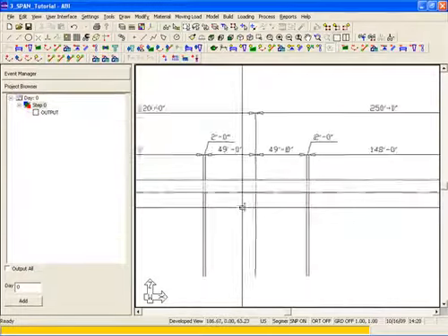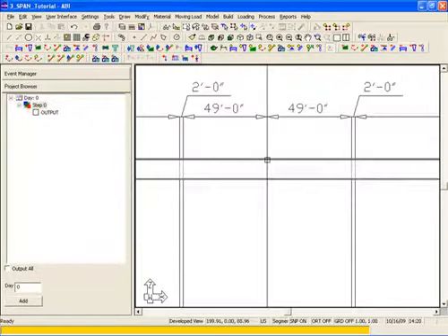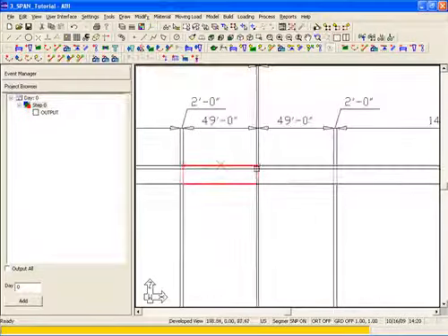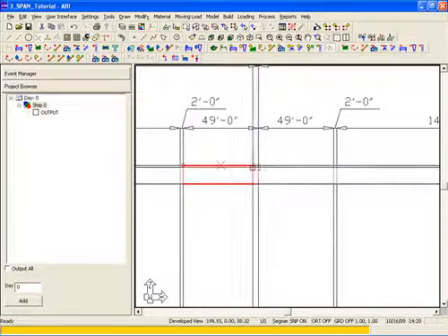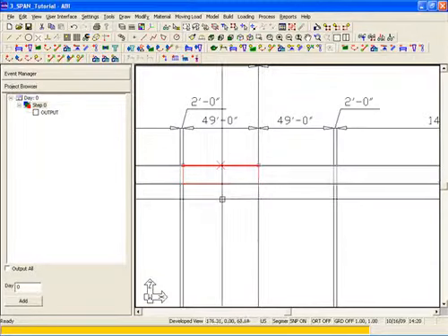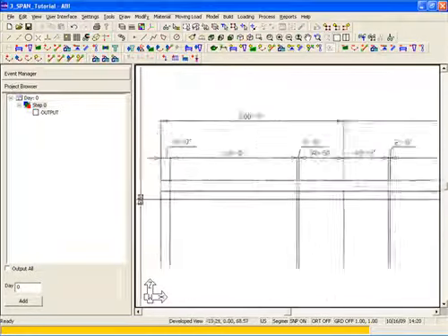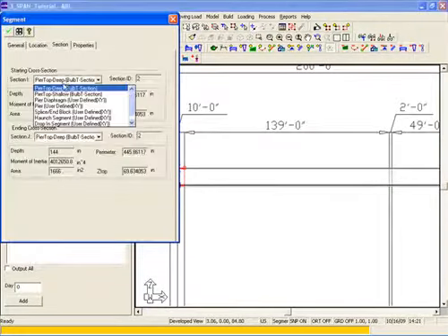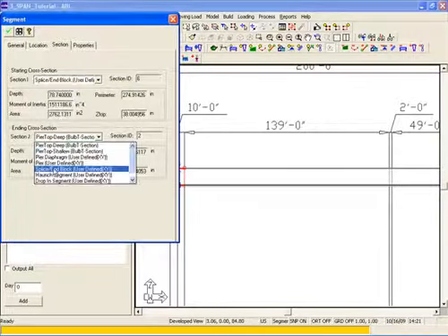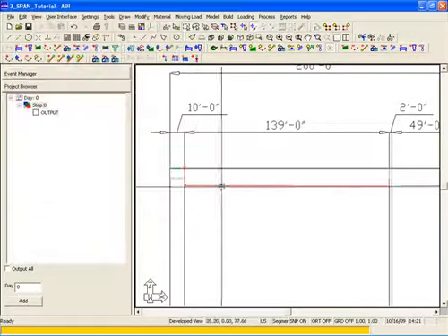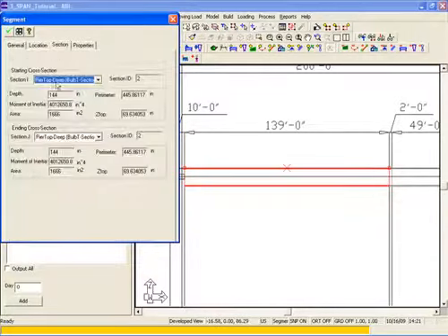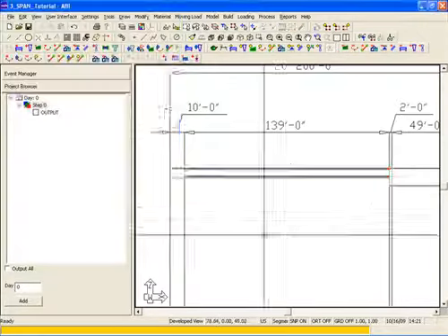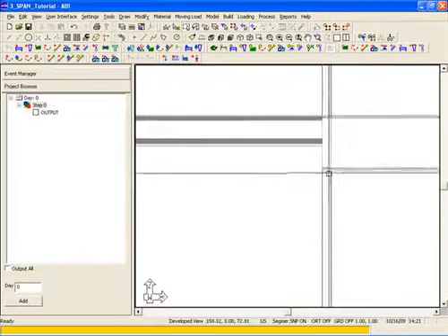One other thing to notice is that there's a pier diaphragm that will be placed here at each pier, but these segments go to the center line of the pier. So we're going to modify those once we've changed all of the different segments. Beginning at the end, this will be an end block or a splice. The next segment will be the drop-in segment again. Now we get to a closure splice.